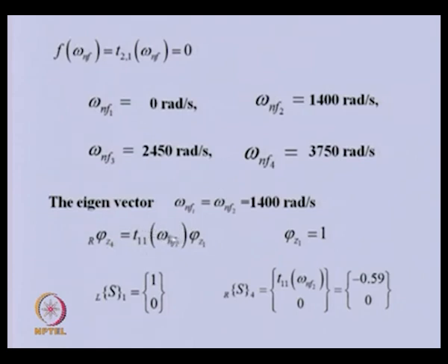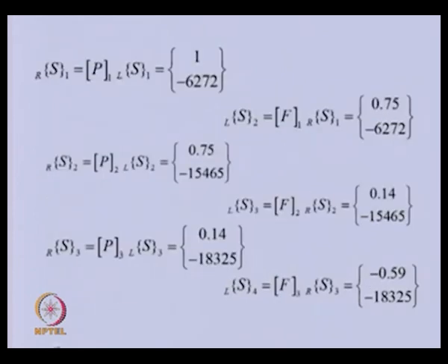These are all matrices which we related earlier. We know the state vector at the left of 1, and we can obtain the one at the right of 4th using this, because we know the natural frequency to substitute. We can march back to get the state vector at various locations, like at left of 2 or right of 2, right of 3. Intermediate transfer matrices can be used to obtain the relative displacement.